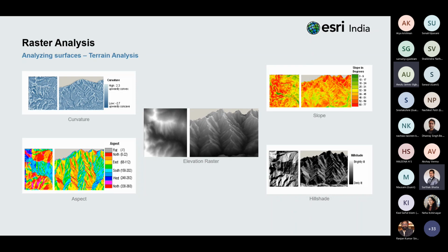That means it is dependent upon the azimuth as well as the altitude, and these two corresponding values are used for shading the image accordingly. Hill shading is a technique for visualizing the terrain determined by a light source and the slope and aspect of the elevation surface.